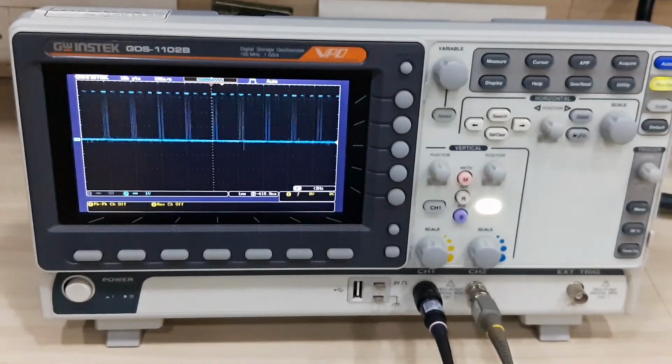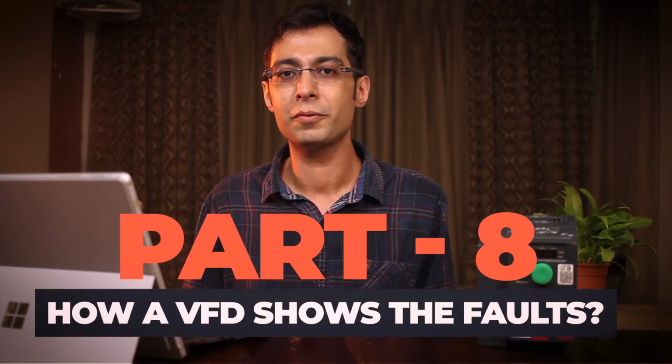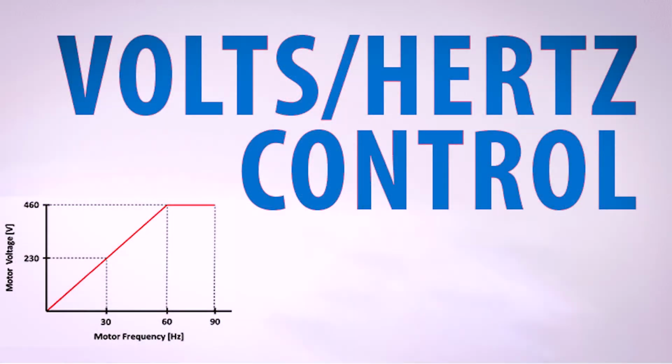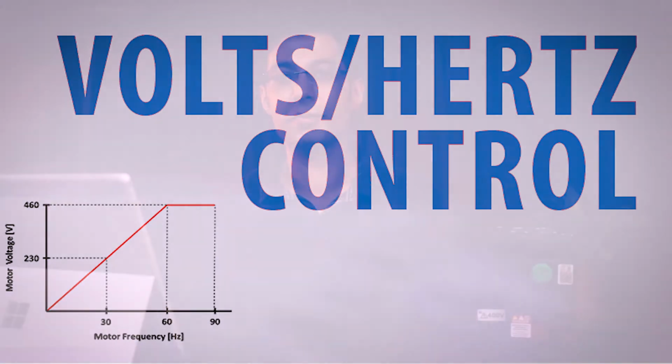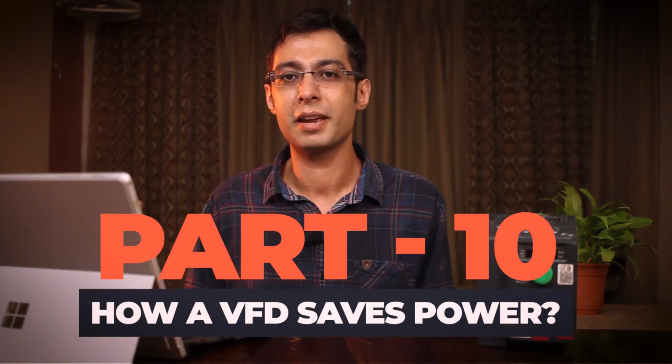It's a technique used in VFDs. And we'll also see the 3 sections of a VFD: the rectifier section, the DC bus section and the inverter section. In part 8, we'll see how a VFD shows you the faults in your system and how you can diagnose a fault and rectify it on site. In part 9, we'll see the volts per hertz control, which is the algorithm used in VFDs to alter the speed of a motor. And finally, in part 10, we'll see how a VFD saves power and pays for itself over the years. So, why do we use a VFD?